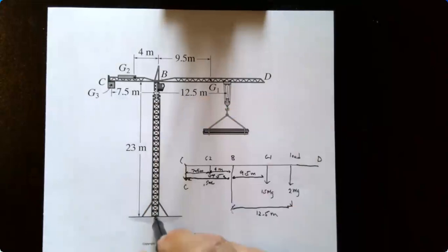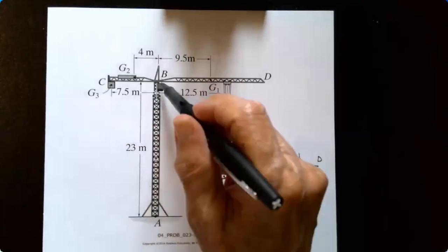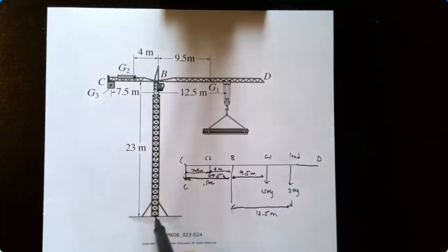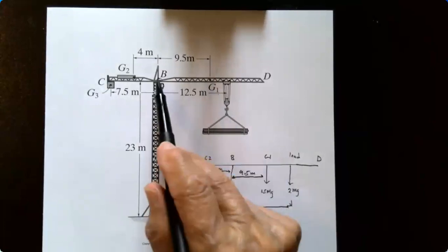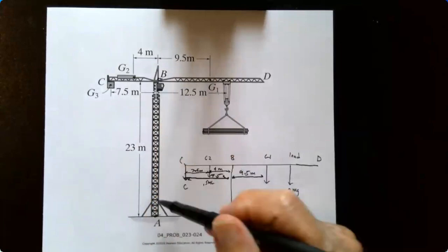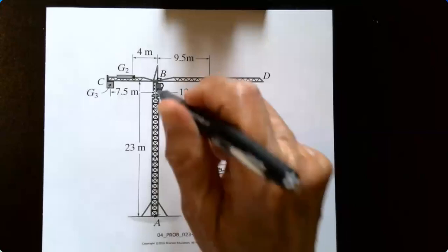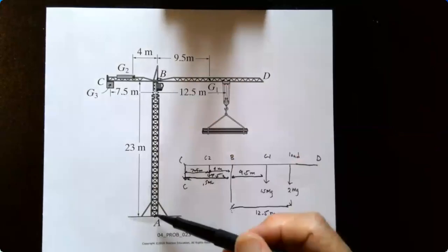The rotation is going to occur here. We don't want it to rotate here. But if you take a look, B is directly above A. Obviously, it's just the tower. The moment arms would be the same as if we took moments about here. So all of these loads, this horizontal distance is the same as if we looked at B, and basically the rotation is about B. So we don't need to show A, we just need to show B. These distances are the same here, and if you took moments about A down here, they would be the same.